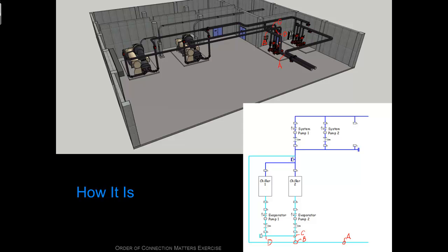document the service valves, the check valves, anything that could affect flow. Like if I closed it, it could have shut the flow off. A check valve keeps flow from going backwards. A control valve modulates the flow. Anything that could affect flow I include on the drawing, any piece of equipment. And so I drop into this pump, I go through the pump, and I come out of it, and I follow that over, and I come to the chiller.